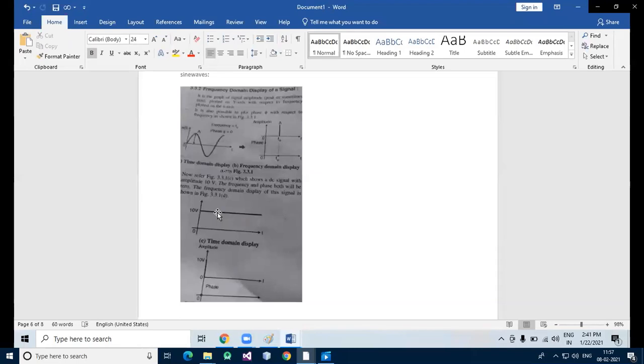So composite signal and transmission medium. The data is generally in the form of pulses, and a pulse is a composite signal which contains many frequencies. Note that the particular shape of a pulse is due to the sum of specific frequencies at specific amplitude and phase. If there are any changes in the amplitude or phase of these frequency components, then the shape of the pulse will not remain the same.